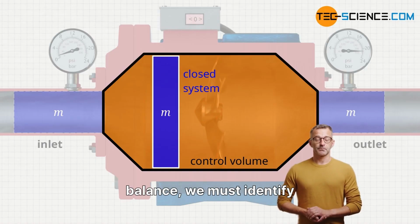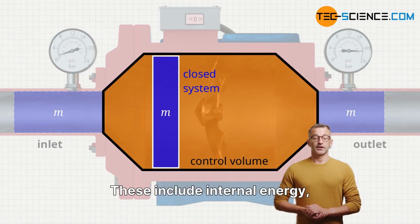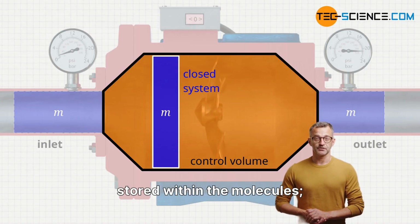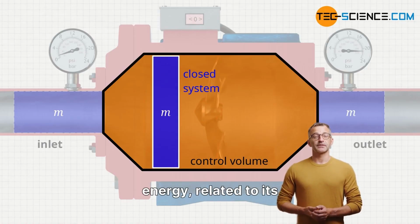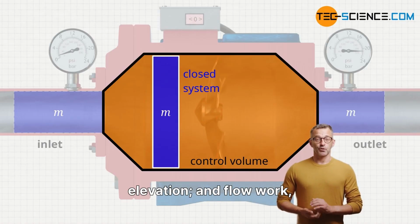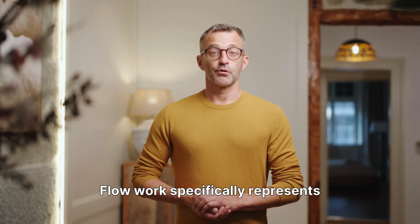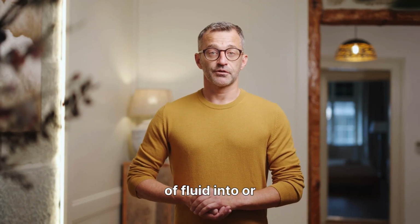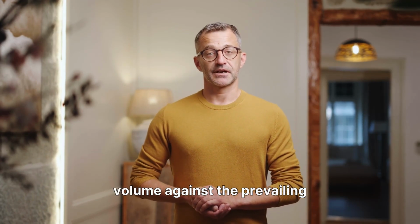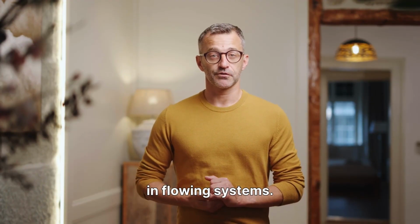itself flows through. To formulate an energy balance, we must identify all forms of energy associated with the fluid. These include internal energy, which is the energy stored within the molecules, kinetic energy, due to the fluid's velocity, potential energy, related to its elevation, and flow work, which is the energy required to move the fluid across the system boundary. Flow work specifically represents the energy needed to push a unit mass of fluid into or out of the control volume against the prevailing pressure forces. It's a critical component when considering energy transfer in flowing systems.